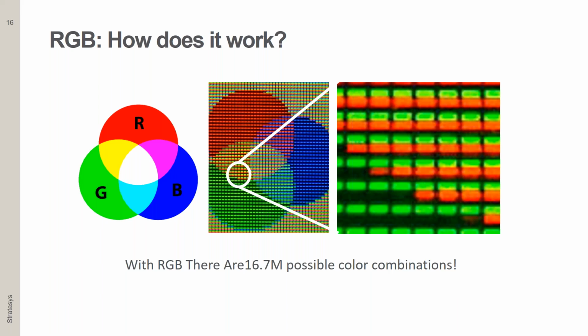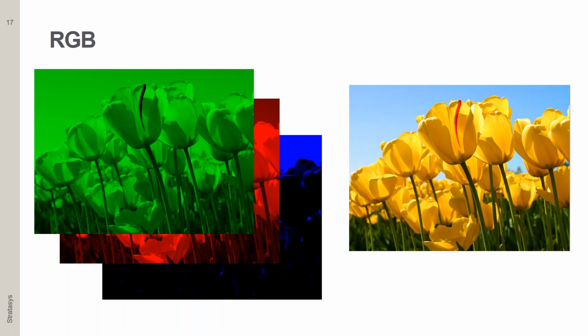So you start from black and you have 3 different LEDs, a red, a green, and a blue one, and they light up with different intensity, and by lighting up, they change the appearance of the color. So all these 3 colors together will result in a nice picture you can see here on the right. You can call that a kind of additive process. You have nothing in the beginning, it's black, and you add light by LEDs on the top to generate a color.